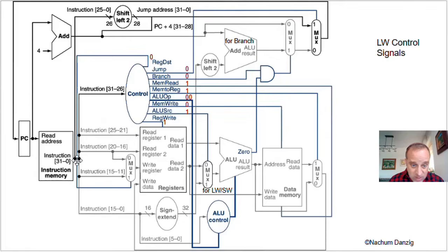We see, well, it's hard to see here, but there's lines coming out. And what we're saying is that the instruction bits 31 to 26, those are the leftmost bits of the instruction, go straight into the controller. Now, the controller, based on that, will eventually push out these values. In the follow-up to this lecture, I'll explain how. But for the moment, let's just assume that it knows how to do that.